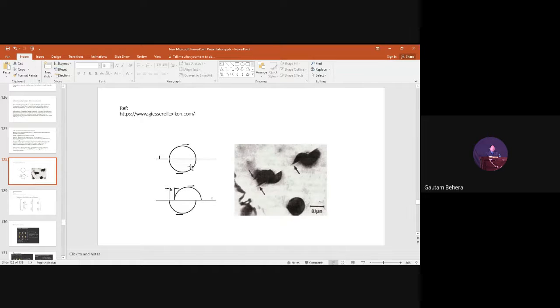So what happened to the interfacial energy and interfacial area before and after this? Increase. How can you say increase? Because new surface is generated. Very good. You can see this is the new surface area, from here to here, right? And from here to here also a new surface is created. Yes or no? This is the new surface area and this is the new surface area. So the surface area will be increasing and the interfacial energy will increase, obviously.